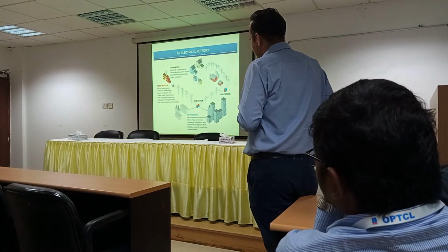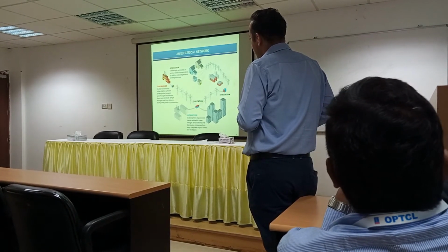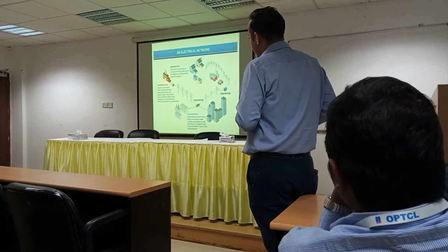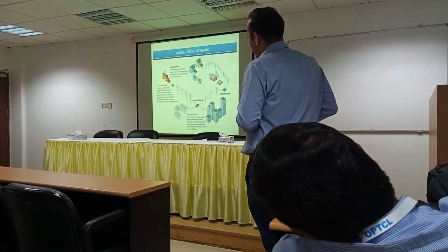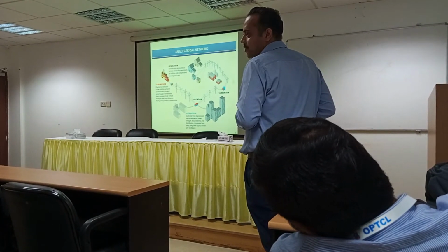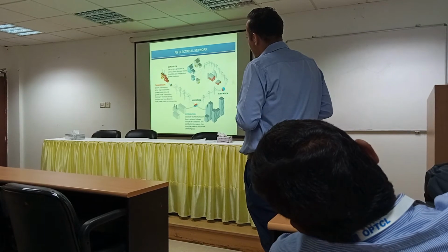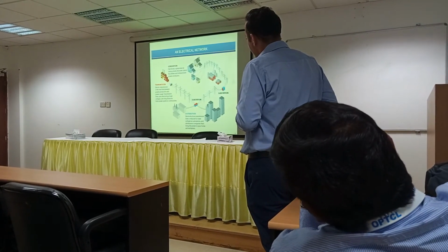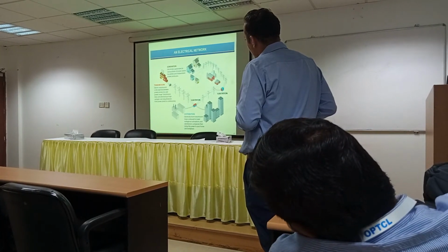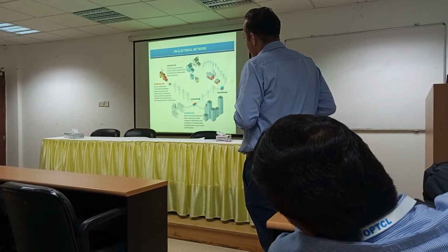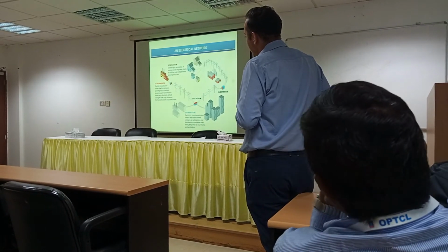Here we have reached a substation portion, with utilities, Discom, and some industry set up. At this particular region, a need has arisen for putting in a substation. This industry needs, say, 33 kV, and the rest will go to another 220 kV substation. So now 220 kV line will be coming in, and we have to step it down.